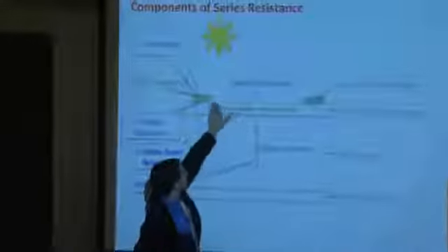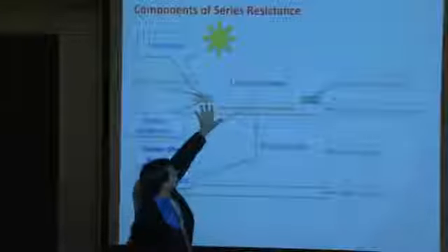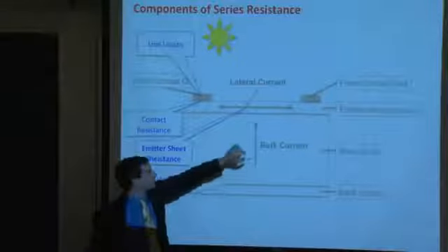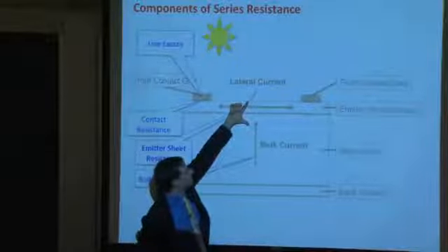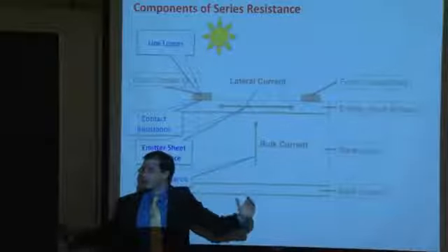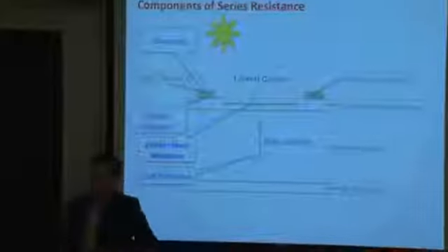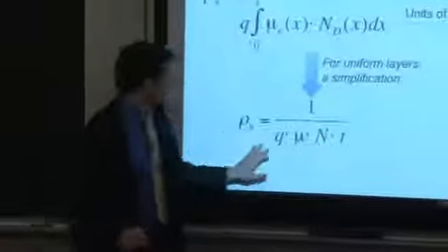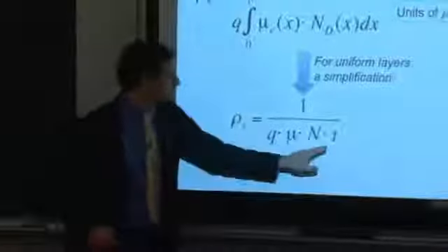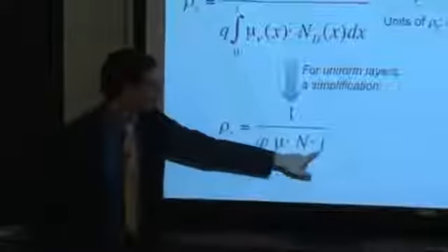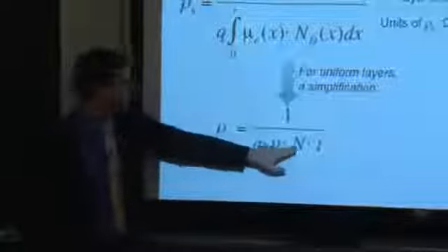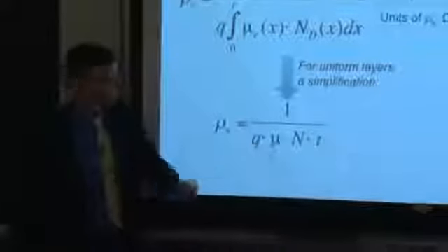We will be dropping the resistance component that carriers experience as they travel laterally through this. And that makes sense, because in effect, as we increase the thickness of this emitter region, we're increasing the total cross-sectional area for the charges to travel through. Right? So folks with me so far, for the emitter sheet resistance to be low, we need the thickness to be thick enough, the carrier density to be high enough, and the mobility to be large enough.